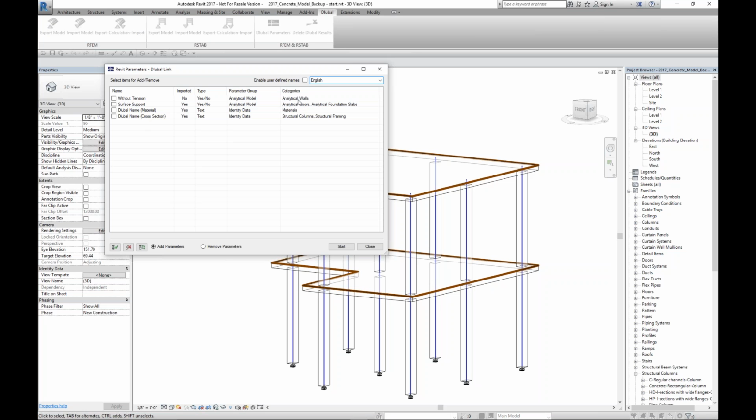Without tension means that the finite element will fail in case of tension stresses, as we find it typically at masonry walls. If a wall has this property, for example, then it will convert it into a tension only or without tension type slab or not slab wall in RFEM, and we have automatically set this type of surface in RFEM.